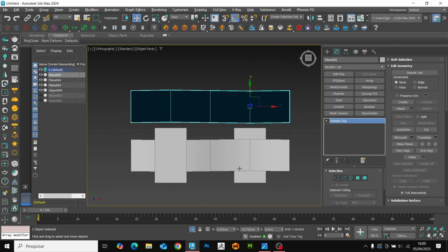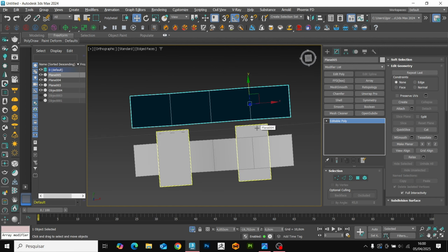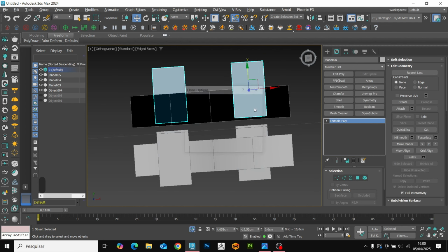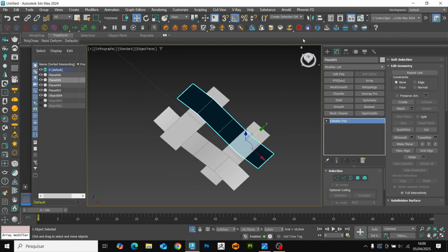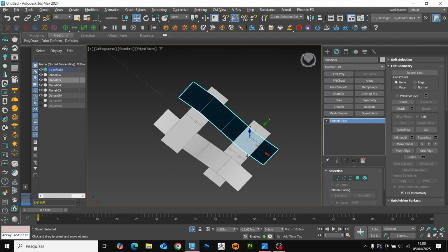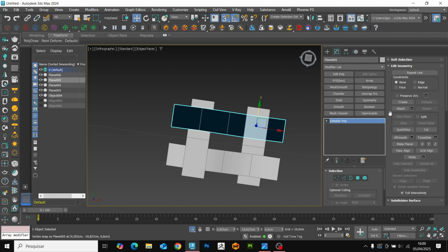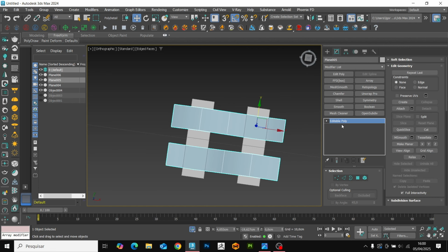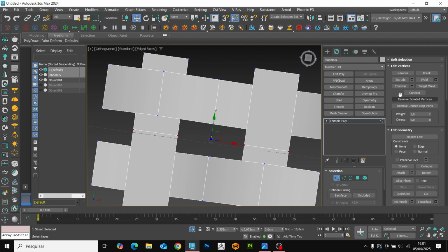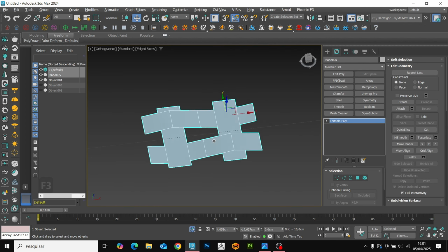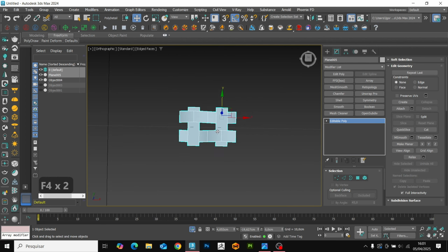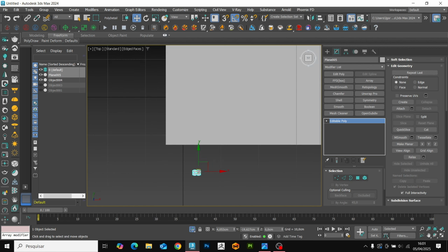We're going to create a copy of our plane. We're going to align it here on the axis. We're also going to align our wave in the center of the object that we created a copy of. Once that is done, we're going to use attach and flip this face, and now we can join the object. Let's weld these points here in the center with the weld and remove these edges. Now we already have our model here for us to create the copies.